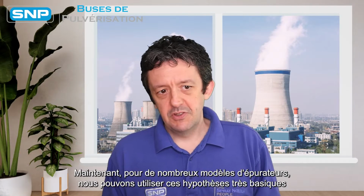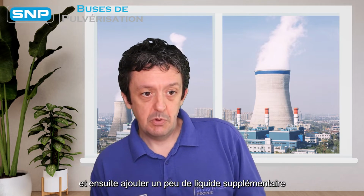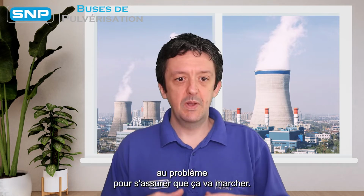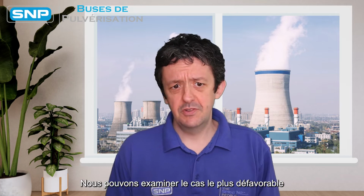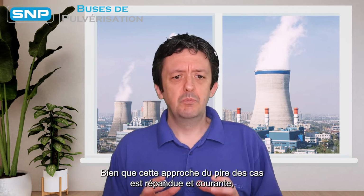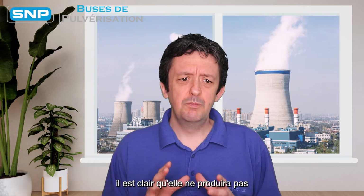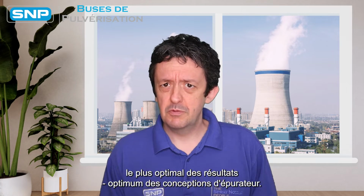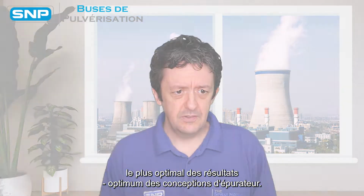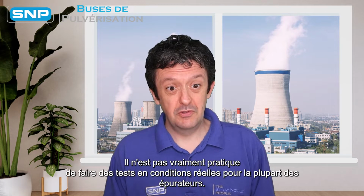Now, for many scrubber designs, we can use these very basic assumptions and then throw a bit of extra liquid at the problem to ensure that it's going to work. We can look at the very worst case assumptions and design the scrubber to cope with those worst cases. Whilst this worst case approach is widespread, common, it's clear that it will not produce the most optimum of scrubber designs.